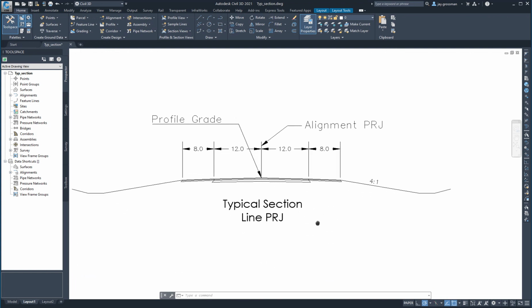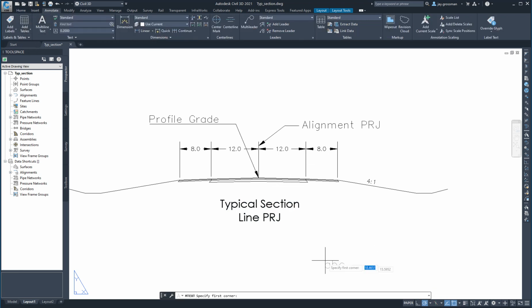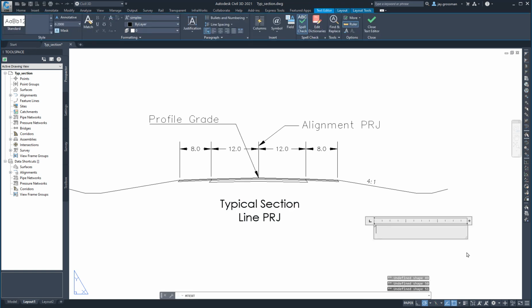If you want to get fancy, you can add in a note over here, an annotation text over what your pavement is. And so this is, well, it's actually 165. If you label it like the sample, pounds per square yard, HMA surface.